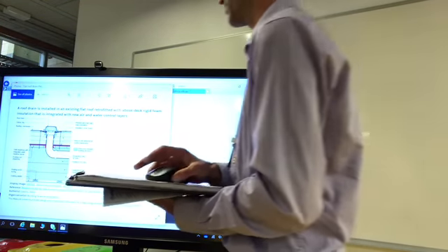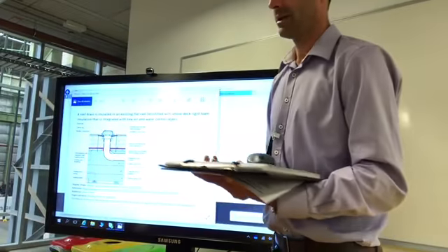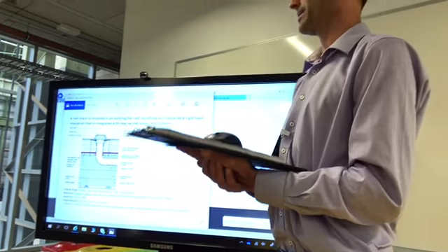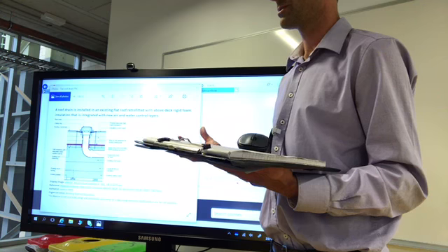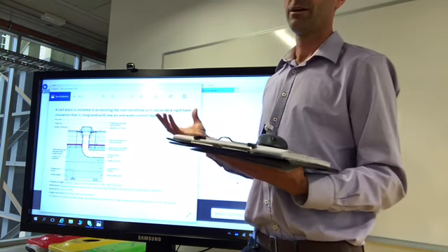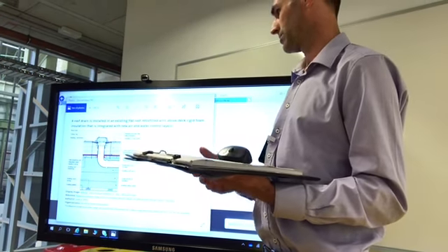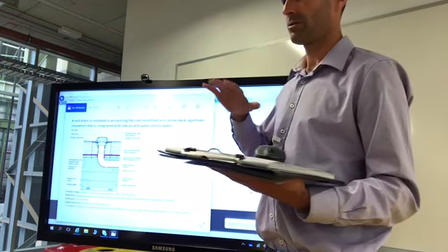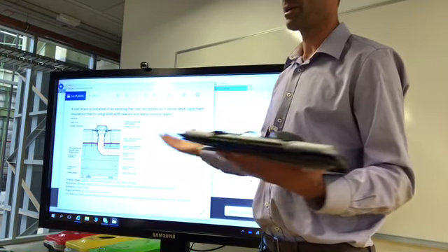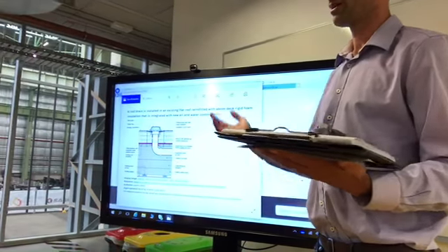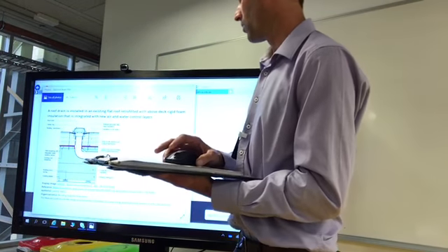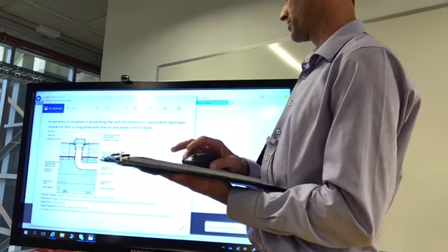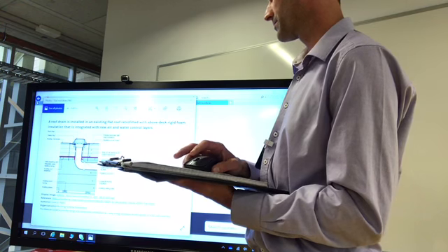Yeah, inviting trouble. But look, I guess essentially, maybe I steer you away from getting too experimental with this roof in that regard. But the options I was wanting to talk about there is if you've got a concrete roof and your EPDM membrane as a non-trafficable roof like this with drainage points, or you look at the box gutter detail.